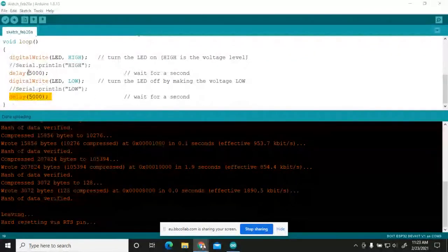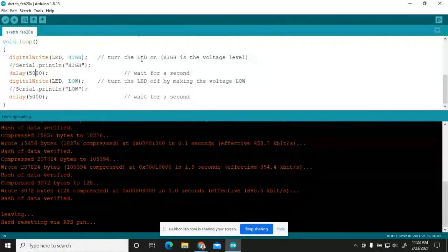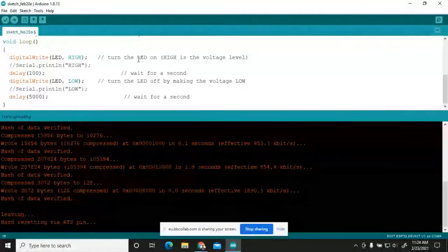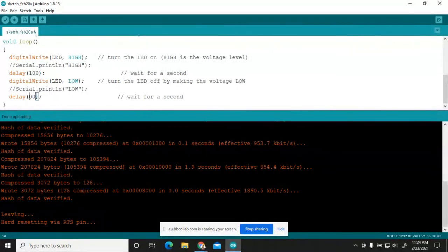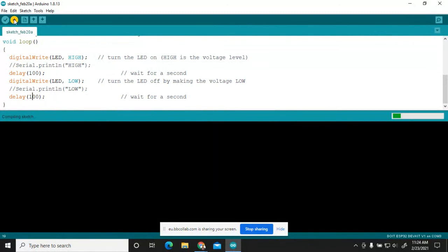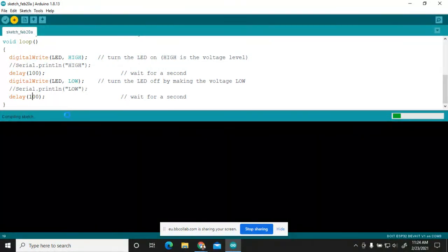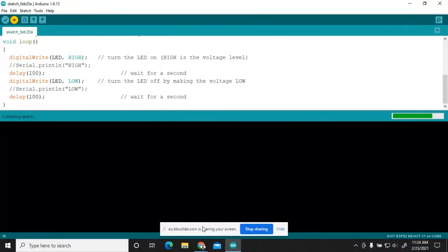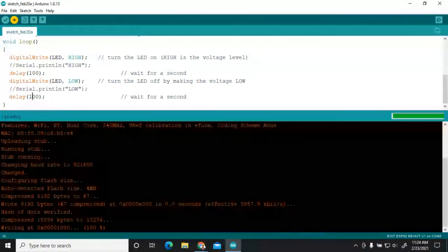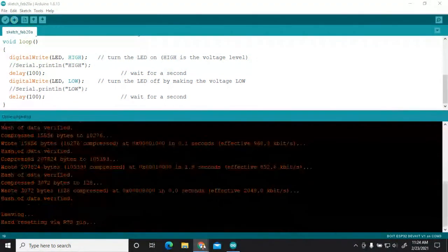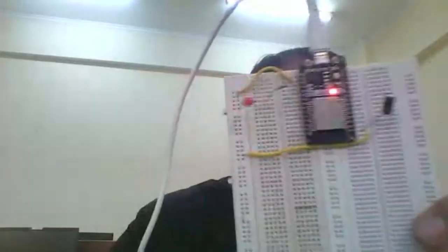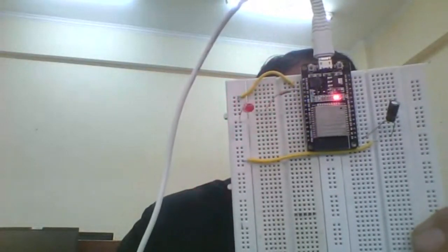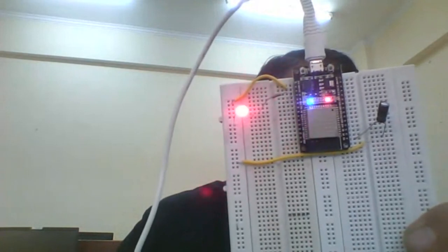This is the program. I'm changing the delay time to 100 milliseconds, and I am uploading this program. Let's see this on the camera. It is uploading. Okay, see the LED blinking. The LED blinking is fast right now.